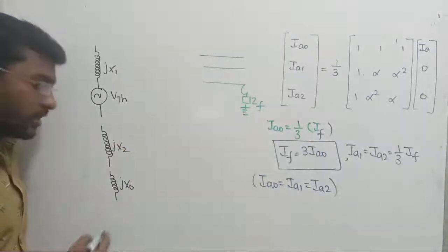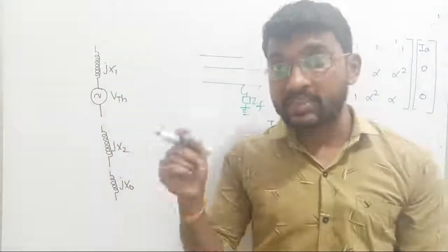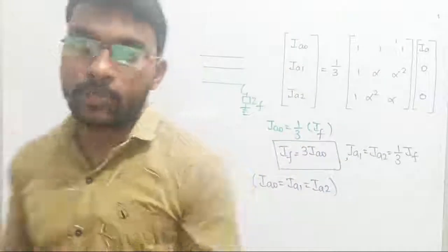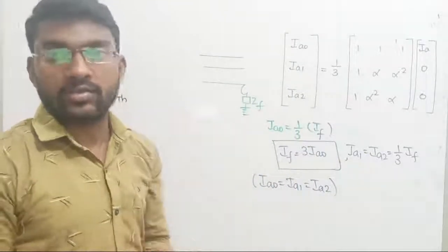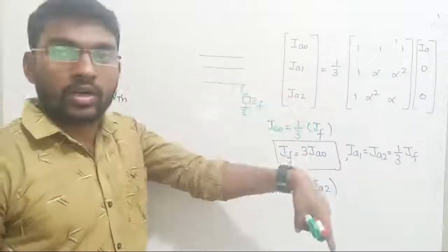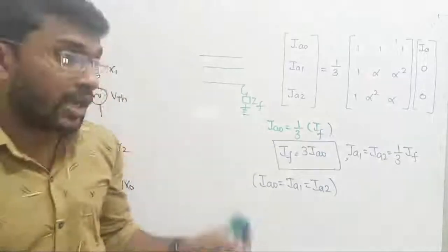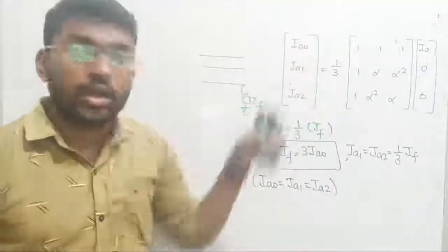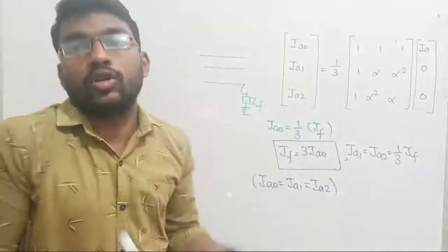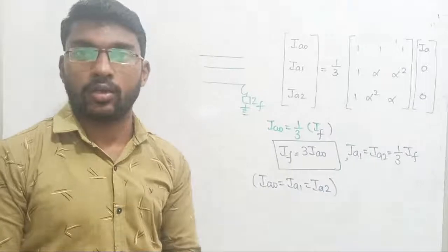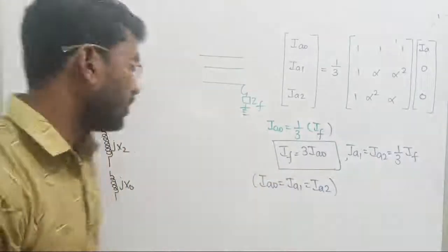With this we will also consider when the zero sequence component will exist. If a ground line exists, the ground line will certainly be there with the fault. Sir, two lines have started, two lines have started with ground also, certainly zero sequence will come. Sir, one line has started directly at ground, zero sequence will come. So whenever I am looking for zero sequence, I have to check whether the line is touching your ground or earth or not. Only then what will happen? A closed loop will exist for the zero sequence current, right? Otherwise it is open circuit. It is open circuit for zero sequence. I have concluded that, right? So it was over.